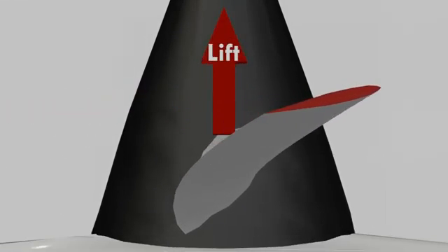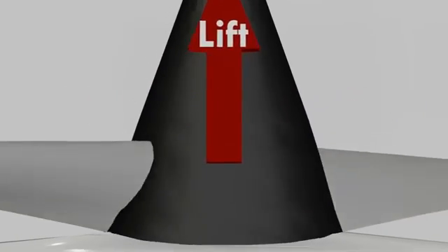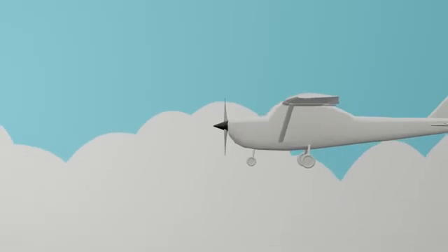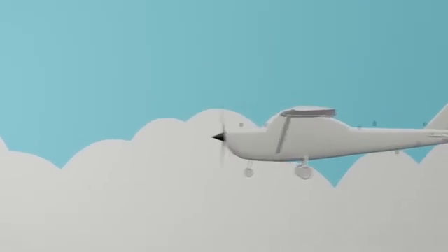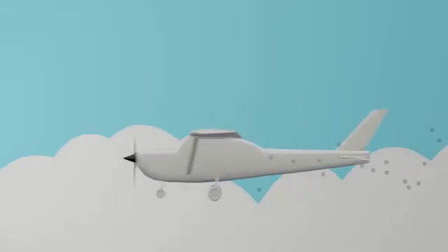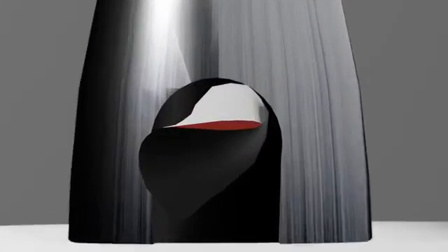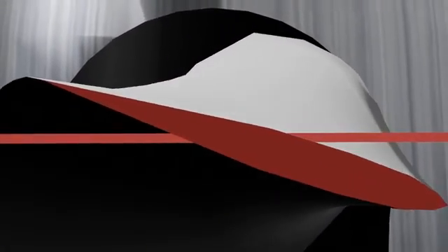This lift can be varied in two ways. If the blades spin faster, they'll produce more lift, resulting in more thrust for the airplane. You're probably familiar with these fixed pitch propellers and their method of control. More throttle means more RPMs, which means more thrust. However, there is a second way to adjust the lift of a wing blade, through its angle of attack.